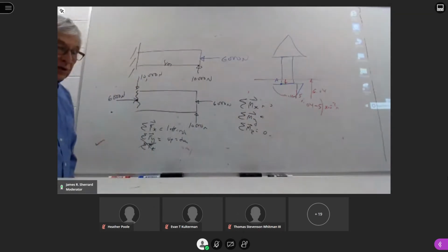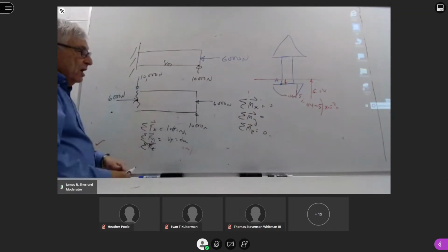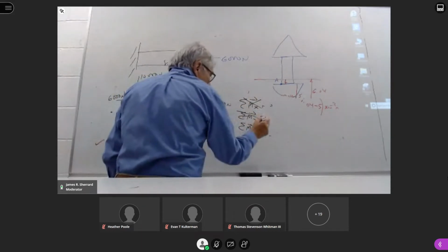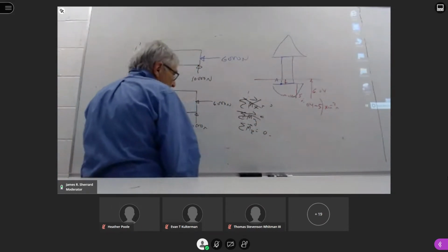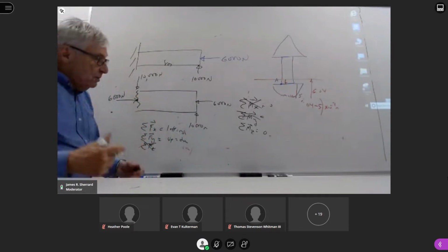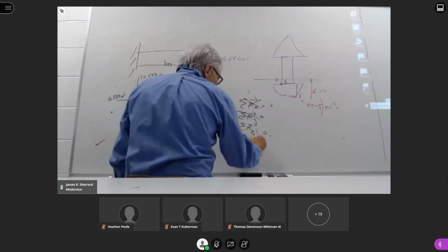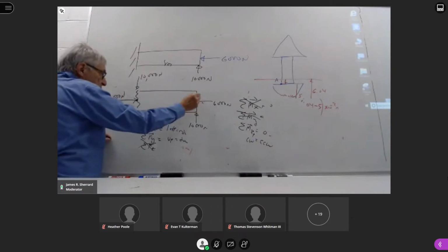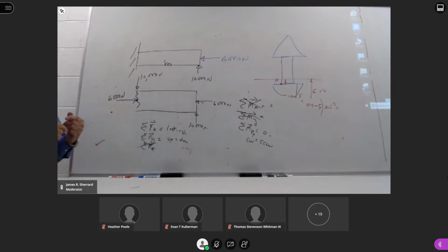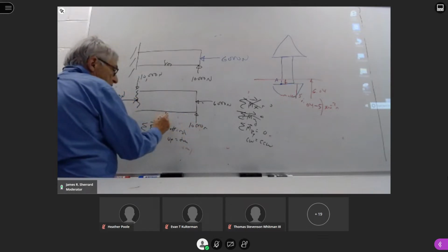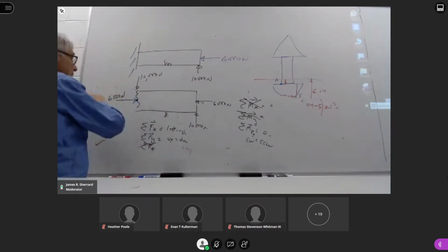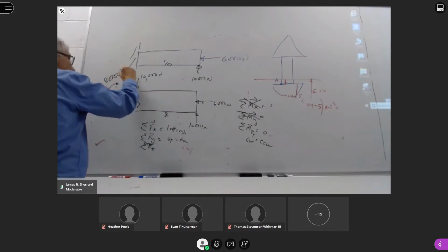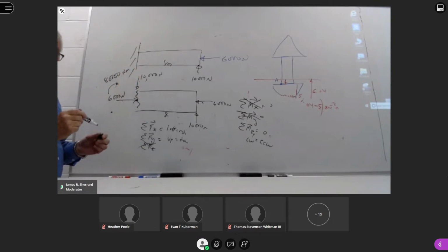And now for equilibrium, they have to exactly equal 0. There's nothing making it rotate around the x-axis. There's nothing making it want to rotate around the y-axis. But there is something about the z-axis, and again, I would typically recommend you pick the point for the attachment point. So again, we'll call that point P, and you know the clockwises have to equal the counterclockwise. If we put our finger here, this force does nothing, this force does nothing, this force does nothing, because again, they go through your finger with no lever arm. This is still the 10,000 times the 8 meters. So this value is still going to be 80,000 Newton meters. This is a complete free body diagram.